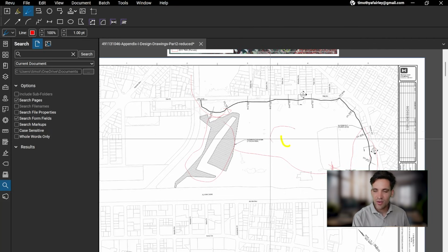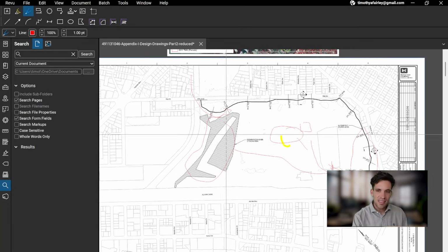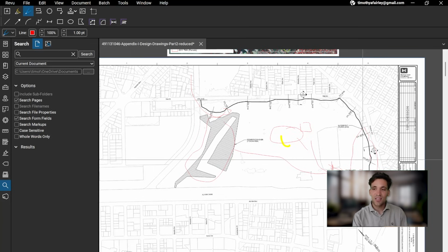Because if you think about excavating, placing it in a stockpile, coming back later, you would need an excavator here to load the trucks. You'd have to drive the trucks and tip off, and you need another excavator here. If you just excavate this portion and then dump it here, you're saving on a second excavator on the stockpile. You're not double handling and reloading materials.